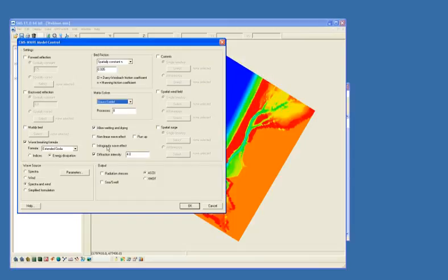There's a simple infragravity wave effect that's been added recently, and you can also choose to change the diffraction intensity a little bit if you need a little bit more or less intensity. You can turn on currents, and you have to pass this information. Normally this is done automatically in the steering module, which we'll cover either later today or tomorrow. You can turn on a spatial wind field, adding in winds. There's another way to do this, and I'll go over that in just a second. And then you can also add in a surge file.